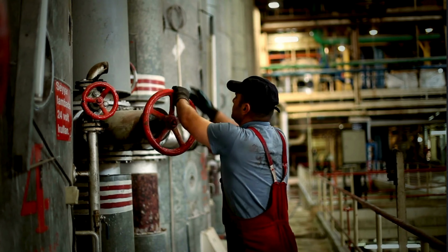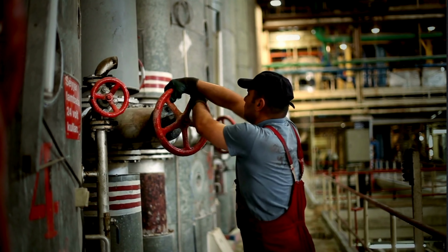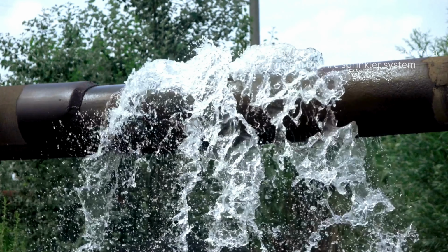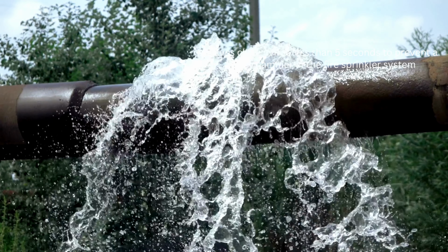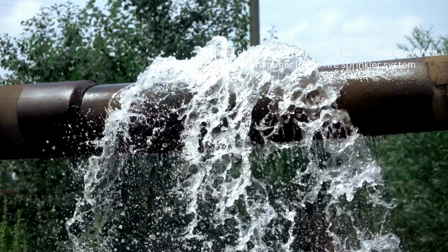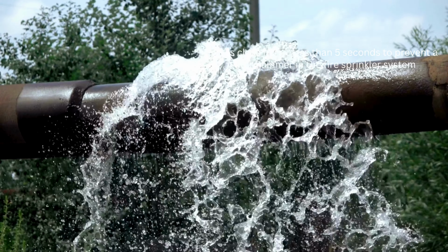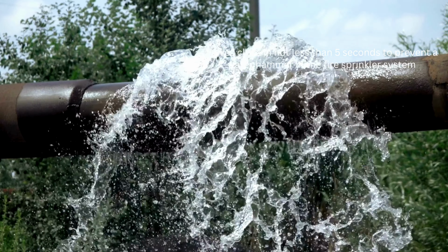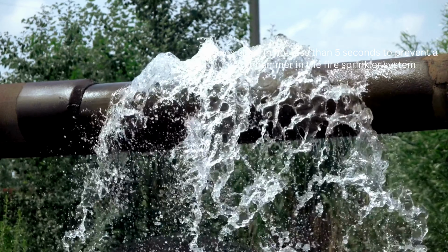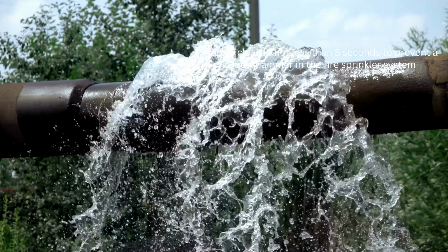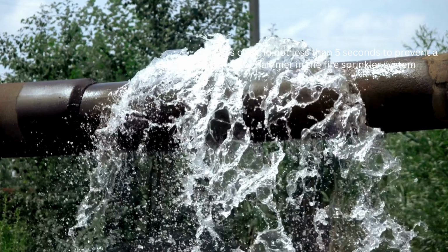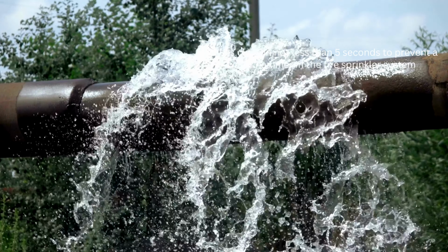Valves close in not less than 5 seconds to prevent a water hammer in the fire sprinkler system. The minimum valve closure time of 5 seconds reduces the possibility of causing a water hammer in a system where water is flowing. Water hammer can instantaneously raise the pressure of the system well beyond the design pressure, which can result in damage to components or leakage. Water hammer, which sounds like knocking in the pipes, can be caused by suddenly stopping the flow of water, causing a pressure surge.